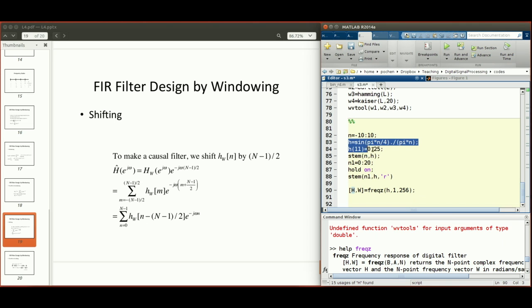And its time domain impulse response is given by this small h. If we want to convert between time and frequency domain representations of a specific filter which has a given impulse response, then you can use FREQZ to convert it into the frequency domain and visualize it. So now let's try to make a plot of this big H function.